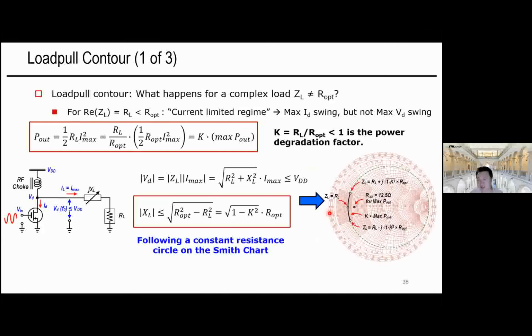Certainly. Here I'm talking about the cases when they are not in phase, when you have a mismatched load and also additional reactance. Just by circuit theory, if your load is not real, they will have mismatched phase, right? So I'm not referring to a desired design case. This is the case to analyze the load mismatch conditions. In actual designs, we always try to make sure they align in the same phase, as you mentioned, so that we can have optimal output power and also efficiency, for sure.